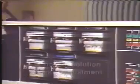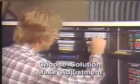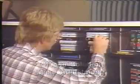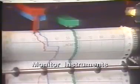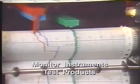Then the operator chooses the best way to solve the problem and makes an adjustment in tower operations to correct it. After an adjustment is made, an operator continually monitors instrument readings to make sure the situation is not getting worse. The tower is given time to adjust to the operating changes, and then new tests are run to see if the products are back on specification.